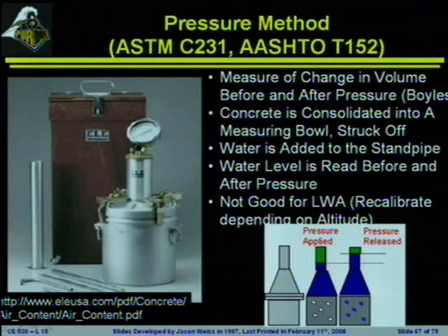In other words, this is simply Boyle's law. The basic idea is concrete is going to be put into this measuring bowl, and the measuring bowl is really on the bottom portion of the system down here. In the cartoon, it's this bottom portion down here toward the bottom. Water will be added above the system.